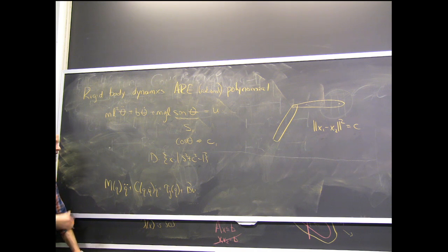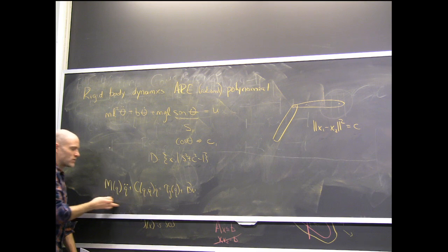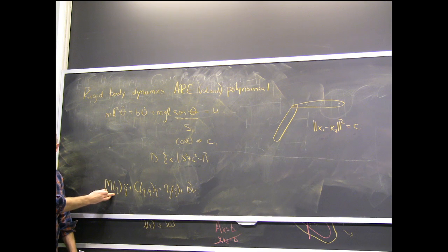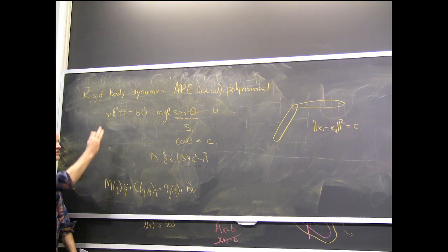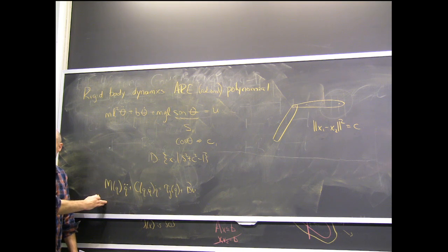Okay, so the more elegant approach in the sums of squares certification, which we're still doing research on today actually, is to just operate with the equations directly in this implicit form. You can try to do the Lyapunov analysis without taking a mass matrix inverse, just working directly on these equations. And in general, there are general strategies for doing rational polynomial.